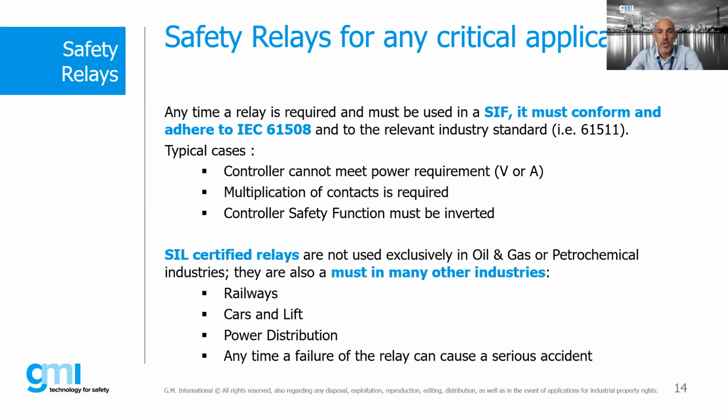But it can also be used when the controller cannot meet the requirements. So when your controller is not able to drive a specific load, that is an application for safety relays. Basically, when you want to multiply the contacts, that is another application. So you have one contact out and you want to multiply it by 2 or 3. Or maybe when you want to invert the safety function, you want to close when you are opening, and so on.